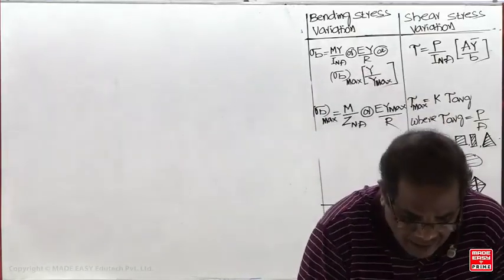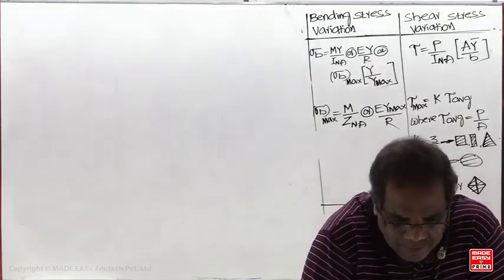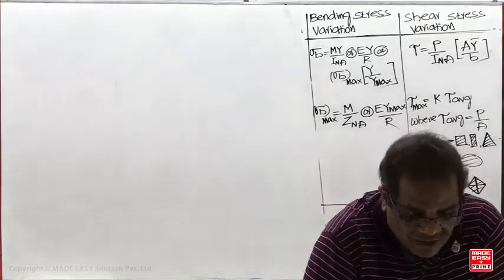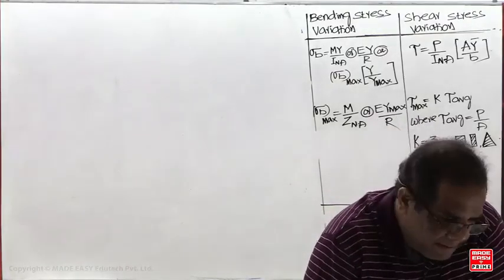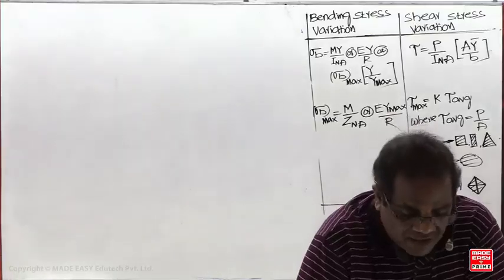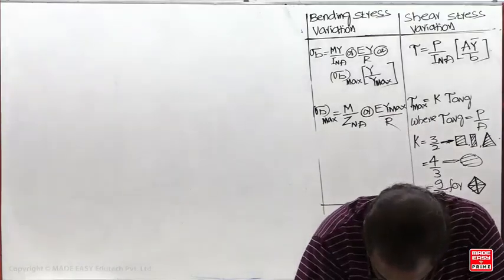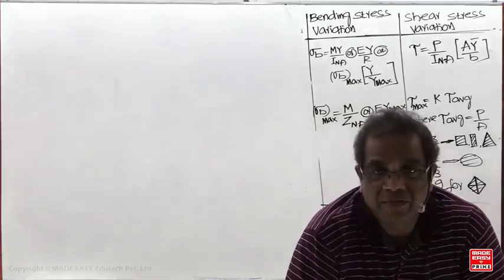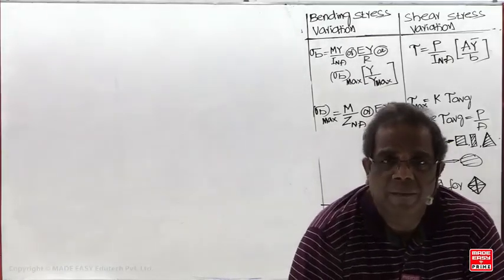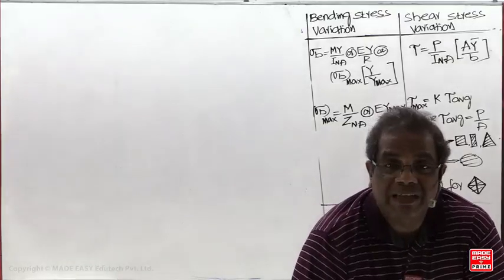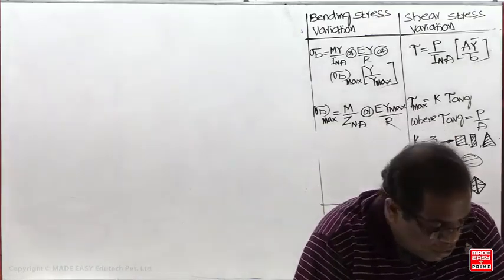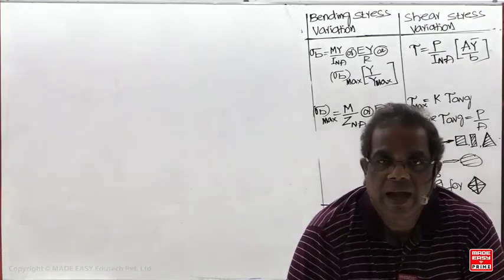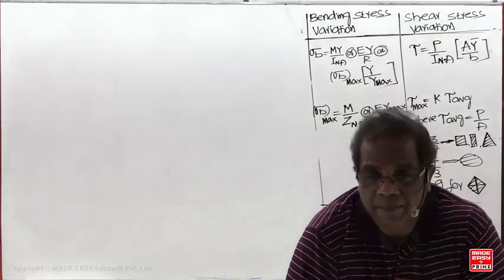Next, under pure bending, within the bracket, bending moment is constant and shear force is 0, a uniaxial state of stress is developed at any point on the cross section of the beam.